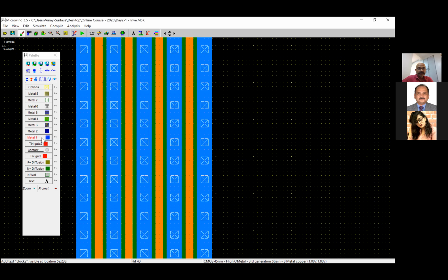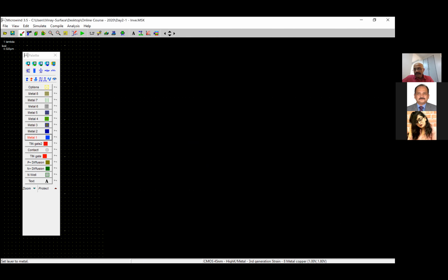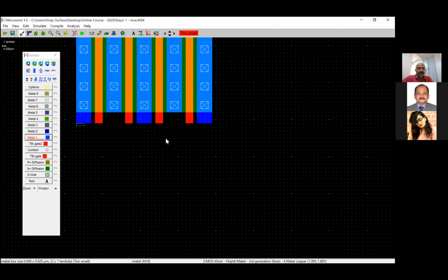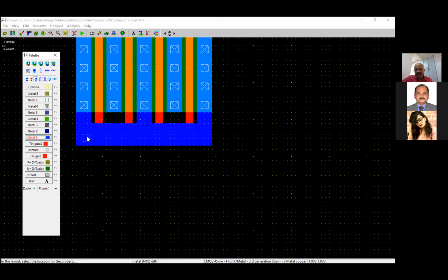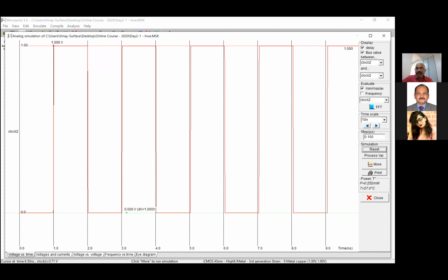It's quite a long transistor. And I short the metal nodes which are extruding from the bottom side, and connect them to ground, this guy, VSS. It should be ready to simulate. I just change the color and simulate this again. I forgot to add the output node.